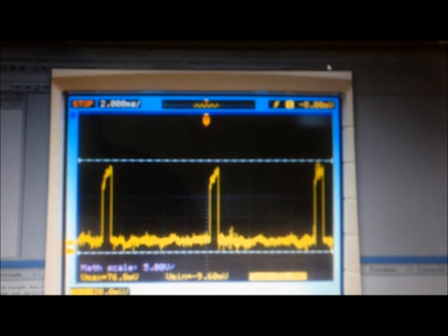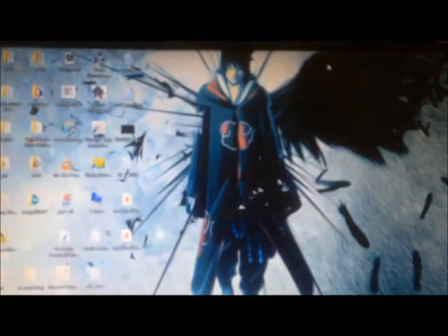The critical part was the component selection. Since we were planning to light up approximately 320 LEDs, we needed to come up with the figures of average and peak currents when the alphabets were scrolled. So, apart from this, we were also required to calculate the average current requirements that would come up on a general message scrolling. So we devised a Python program.